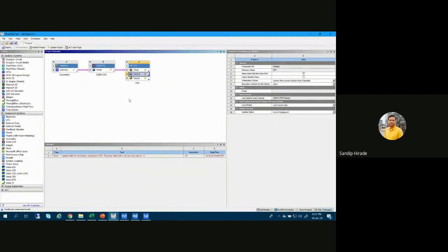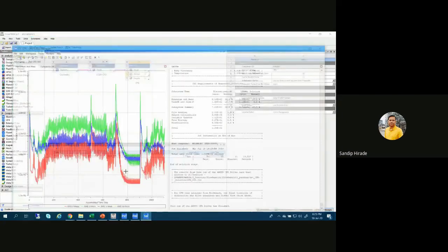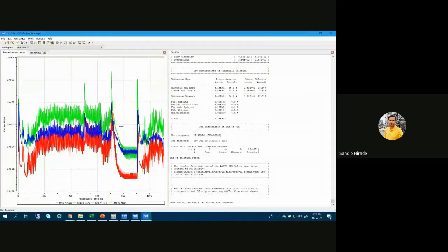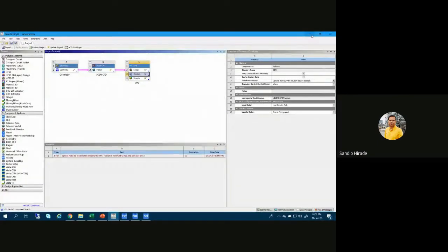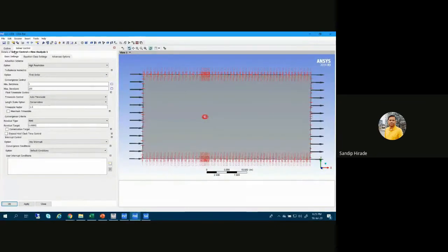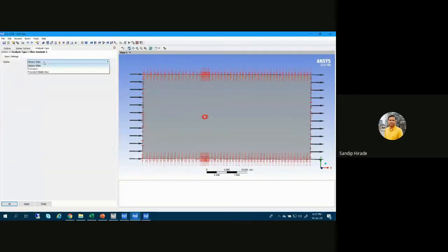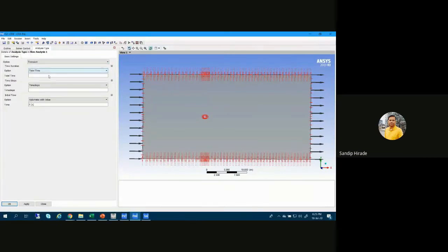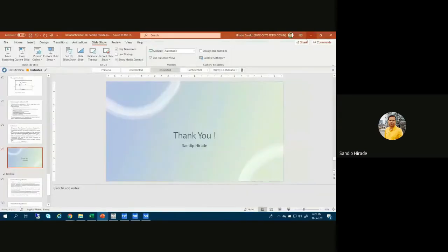And now the flow over the cylinder is not a steady phenomenon. We are solving this as a steady phenomenon. Basically, it's a transient phenomenon. However you change the controls here, you will never see steady residuals, because the physics itself we are modeling wrong. We have to solve this problem with the transient settings. That is where you can change your analysis type to transient, and then you can have the oscillations and time variation in your solution.